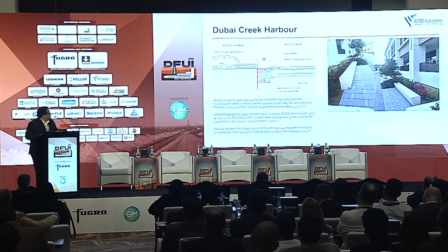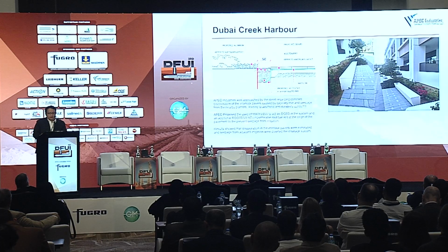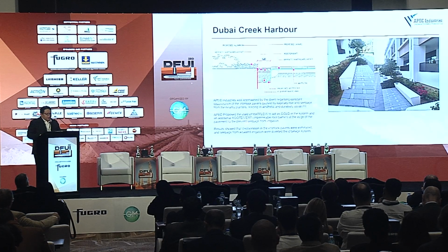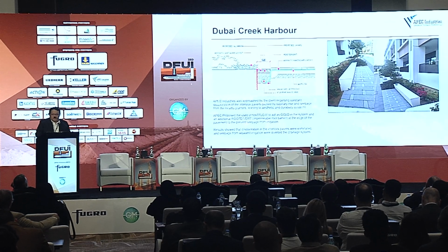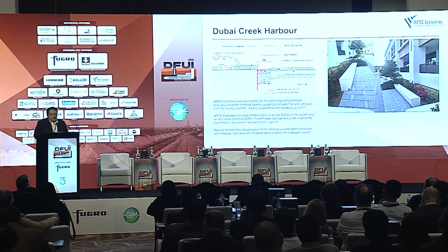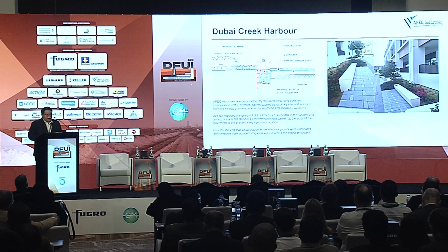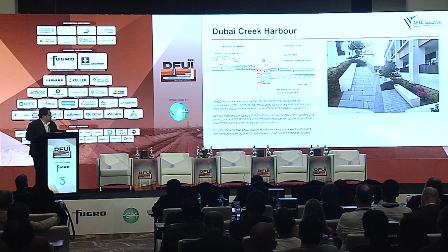So one application is in Dubai Creek Harbor, where hardscapes and pavements have constantly experienced discoloration, efflorescence, and durability concerns due to capillary rise and seepage from adjacent planters. So APEC Industries have provided an engineering solution using 3D monofilament geocomposites under the interlocking pavers and providing the required capillary break and drainage for the system. This in turn is connected to a drainage system, and in addition, an additional impermeable root barrier has been installed in the areas adjacent to the planters to prevent seepage from irrigation.